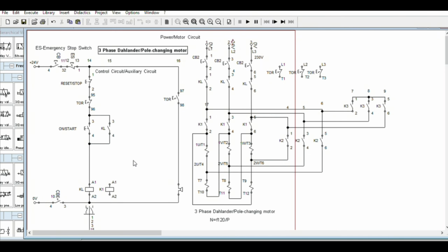That means all the control contact auxiliaries are under these two momentary contacts. So we have four contactors, so we need two more. If the transition from low to high speed is semi-automatic, no timers, you can use a push button.